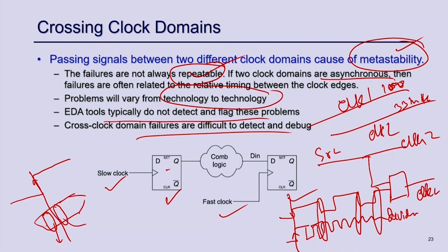So, this is called setup time and this is called hold time, right. This is hold and this is setup time, and if the data toggles in this period, right. So, this is the boundary, at this boundary even if the clock comes at this point, this is the point where your data state does not change, right. But if your data state changes here, then what will happen? It changes from 0 to 1 or 1 to 0, and that is causing the metastability,